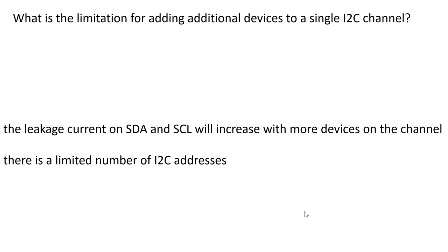But also, there's a limited number of I2C addresses. The address space is quite limited, 7 bits basically, unless you go to extended mode. The I2C address is actually addressing the device and the internal register in the device. That's a problem. That's why they have extended mode, which I think uses a 10-bit address. But even then, that's only 1,024 total addresses amongst all the I2C devices.